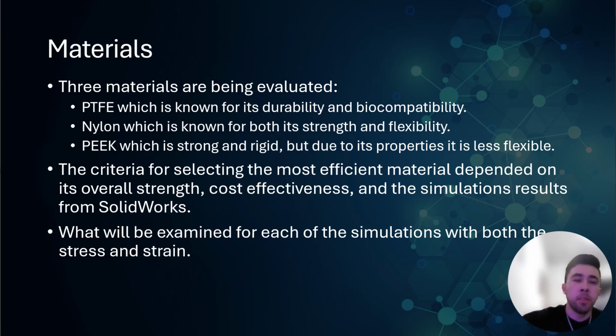So materials. The three materials being evaluated, found through research, are PTFE, which is known for its durability and biocompatibility; nylon, and since they didn't have regular nylon in SOLIDWORKS, as a substitute I used nylon 101, which is known for both its strength and flexibility; and PEEK, which is strong and rigid, but due to its properties, it is less flexible.